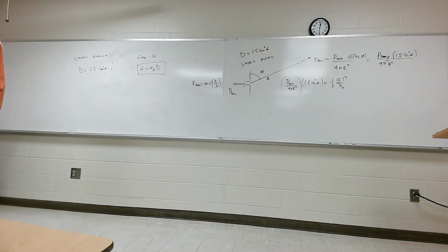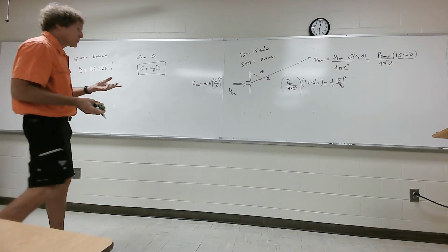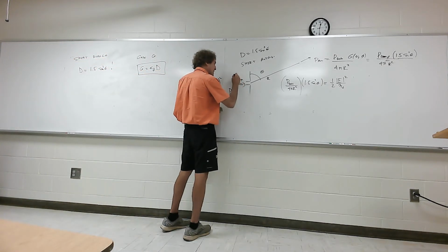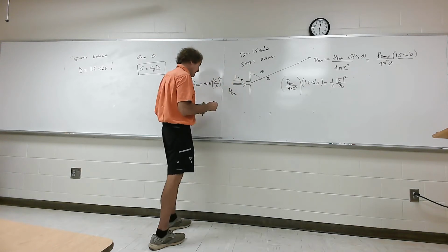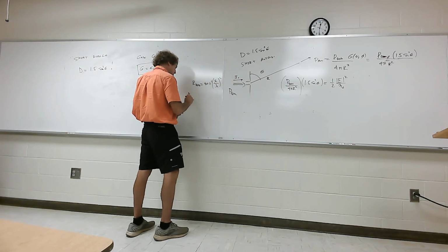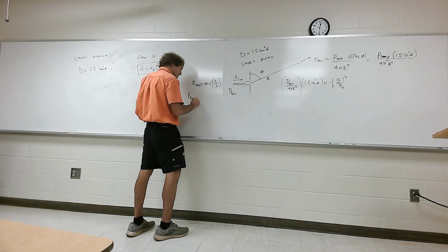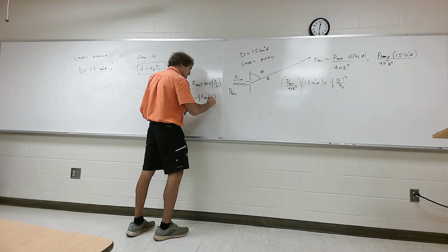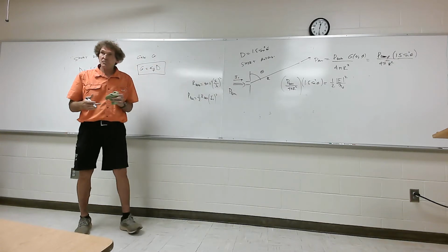The truth is a short dipole has a reactance that dominates, that limits current. And I'll get into that later. But if you want the total power transmitted, if I give you the current I here, I naught is a peak current, then the total transmitted power would just be equal to 1/2 R rad times I naught squared.